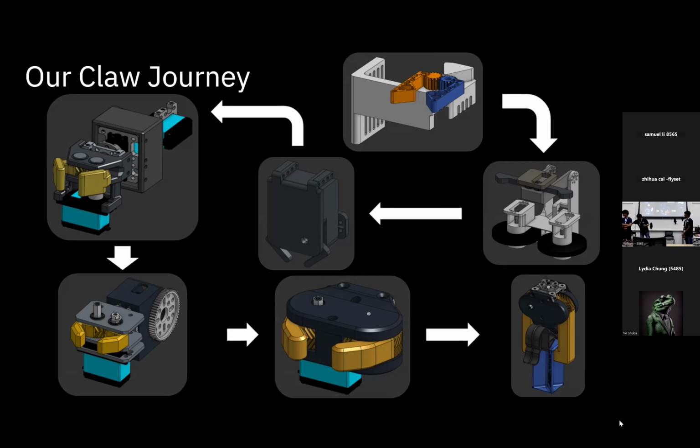So in the past seasons, very recently, there have been many teams who use custom chassis. One very common version of the custom chassis is a parallel drivetrain, right? Now, why should I do a custom chassis when we can buy parts from goBILDA and just put those together? Well, you should do a custom chassis because you can customize how far apart each of the holes and each of the motor placements are, right?